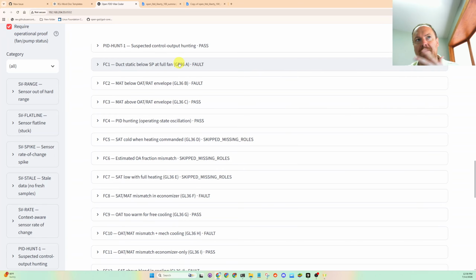So we do a little bit of data modeling, something kind of Haystack-like. We use Haystack naming conventions, and then we map the CSV column name, the raw point name, to the Haystack name, and I used AI to do all of that mapping for me. And then I iterate over the faults that would apply to the air handling unit. So this is what it means by skipping.